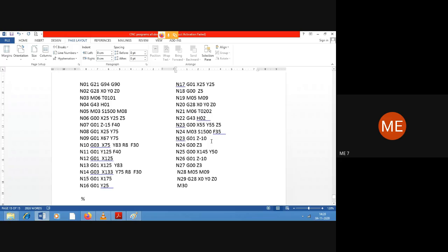And then, at this particular coordinate, the tool has to be inserted, that is, the tool has to be moving vertically downwards until Z is equal to minus 10, okay, right? And then get it out, G00. Take the tool out, so G00 Z5.